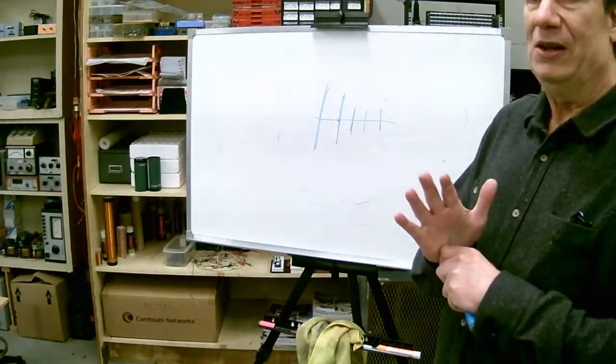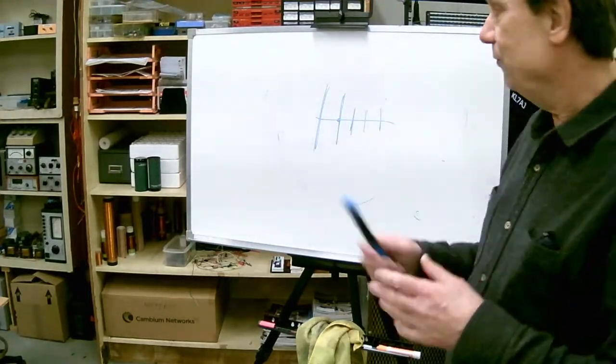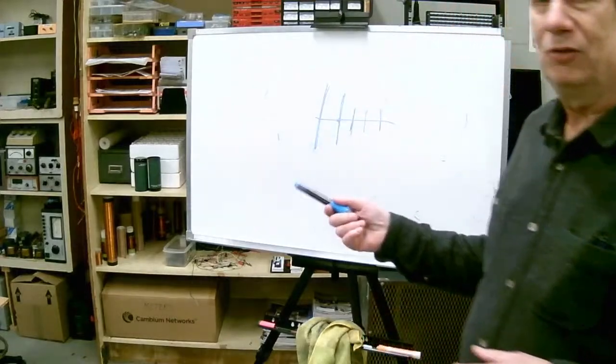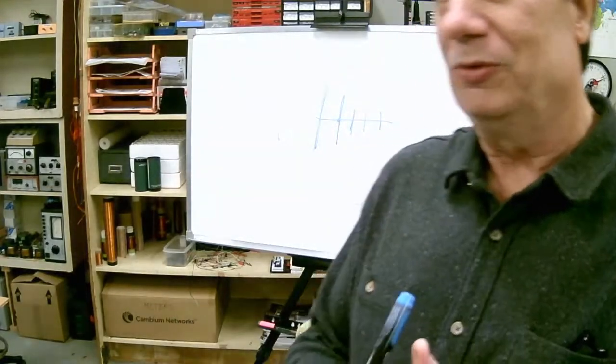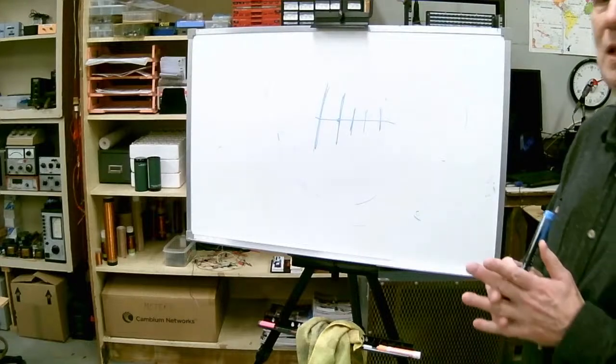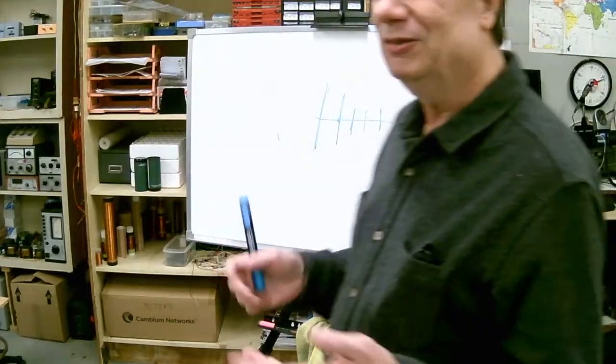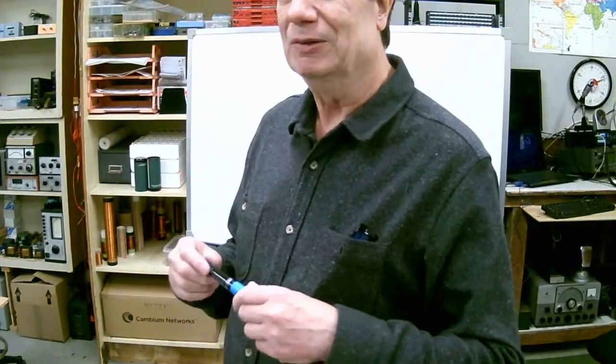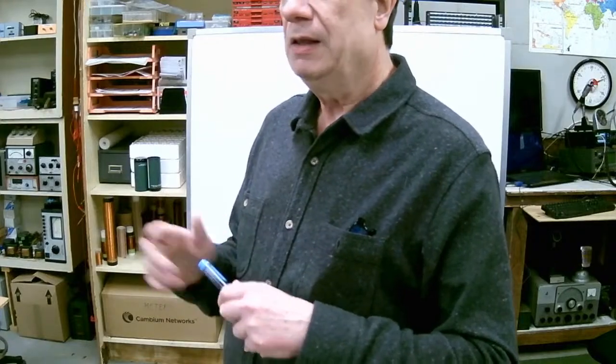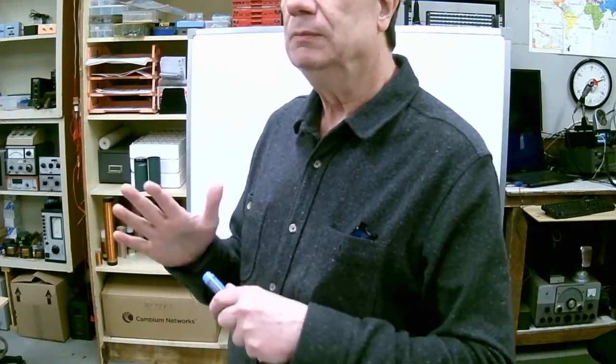That's only for impedance matching, because when you have elements that are close to a different element, it's going to bring them much lower than 72 ohms. So that raises it back up again to a reasonable value. So is that 900 megahertz? Yeah, 900 megs.